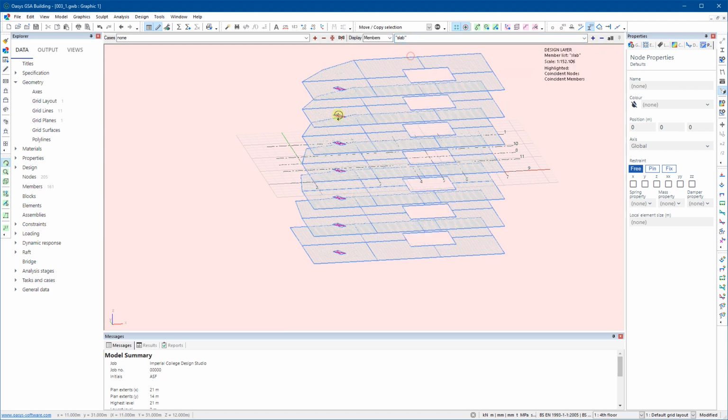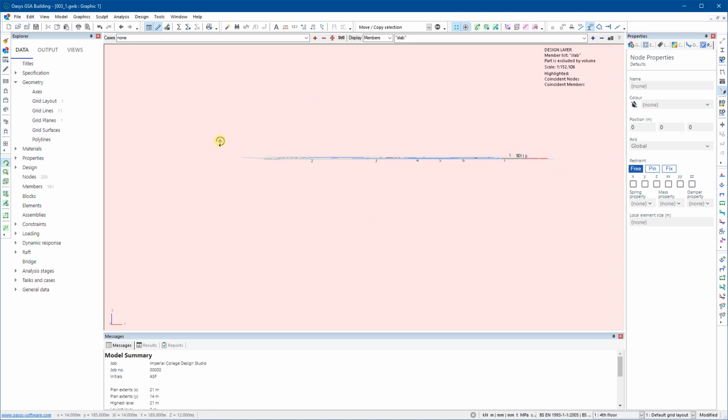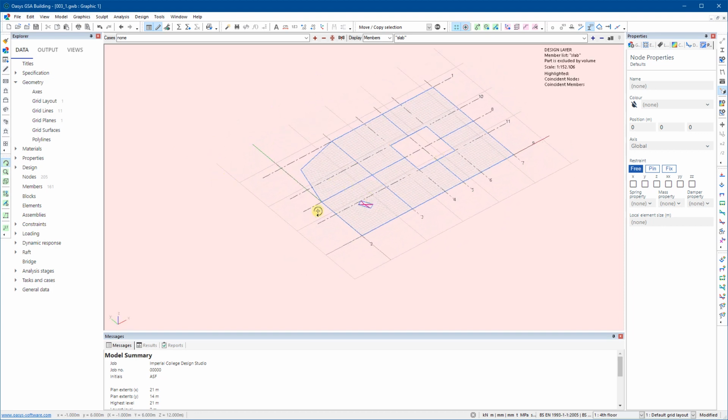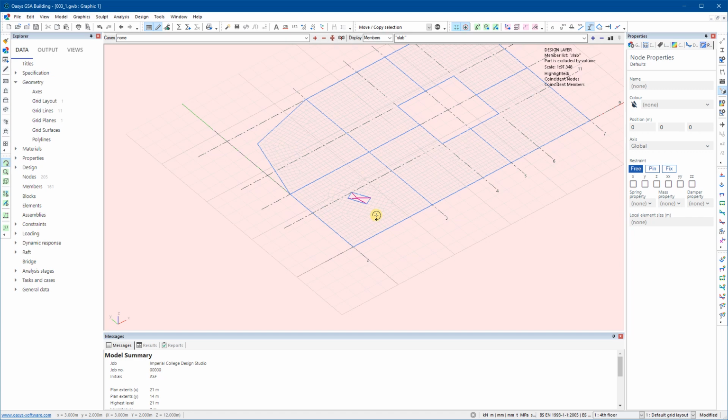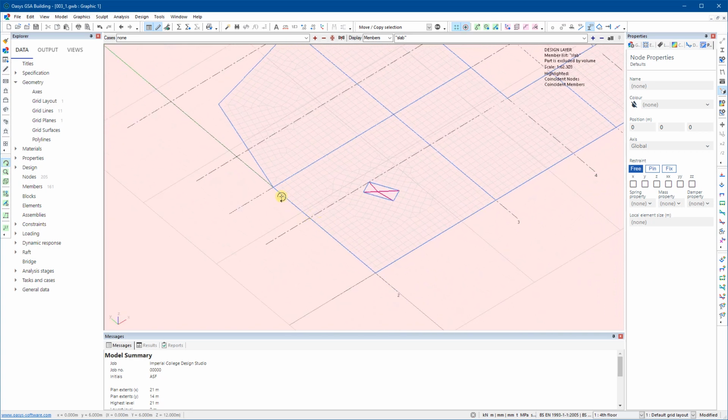Excuse me. So if we look at the slabs, using the volume tool, 1, 2, 3, the 4th floor again, it's got the grid along it. So that's the 4th floor. Again, I'm going through this pretty quickly. It's basically stuff I've covered in the last video. But what I want to do now is to add in a beam, say along one edge here. This is just for purposes of examples a bit later in the tutorial.